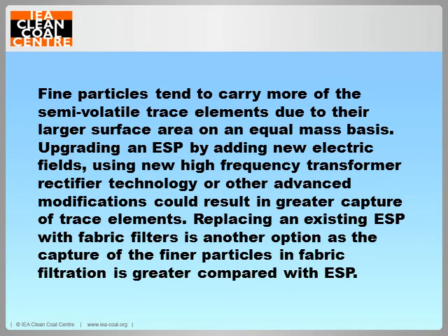The choice between electrostatic precipitation and fabric filtration generally depends on coal type, plant size, and boiler type and configuration. Both technologies are highly efficient particulate removal devices with design efficiencies in excess of 99.9%.